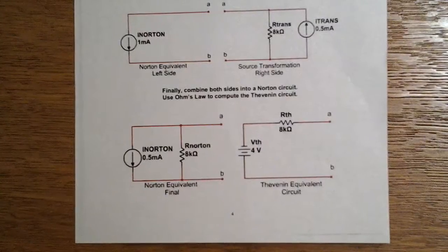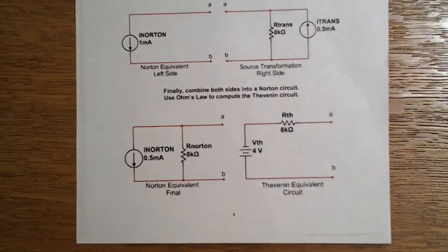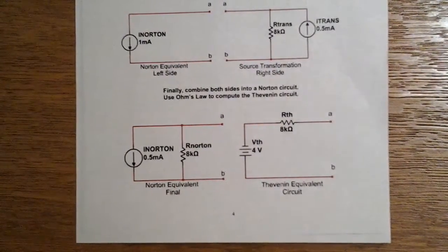Current, no. So I was going to generate a second voltage with the same characteristics of the 1 milliamp source. Unfortunately, that did not work. For this circuit to work, we needed 2 independent sources. And the MyDAC sources are not independent. They share a common ground. Every time we connected the voltages up to opposite polarities, it would short out. Hence the need to use a battery and a variable resistor for the second source. Once that problem was solved, everything else went as planned.